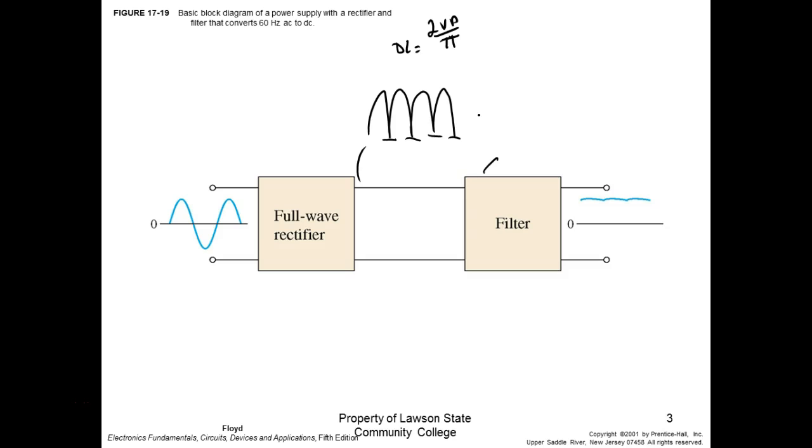We never go to 0 volts anymore. So what we end up with is we never see the original charge because it charges up through the transformer. As soon as we turn power on, this guy's going to be charged, right? And then from then on, we get this right here. We call it a ripple voltage, but it's not quite a sawtooth. A sawtooth would look like this. So this is not a sawtooth, it's actually the discharge of the capacitor. So it comes up here, and then it discharges. It's got a slight slope.